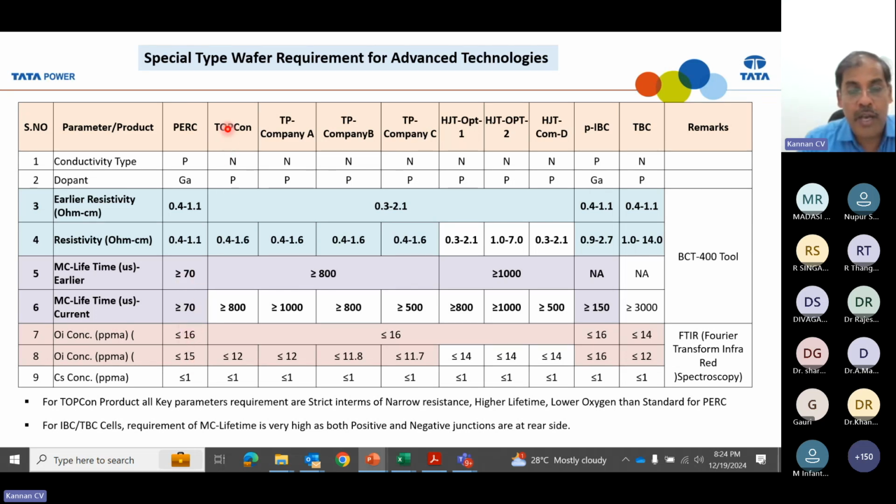But when you go for high efficiency technology, TOPCon, which is currently the mainstream high efficiency technology, and HJT, all these new technologies are based on N-type product. They are not using p-type based substrate. A few years before, all the grown ingots were p-type. Now the entire industry is moving from p-type ingot growth to n-type ingot growth, because n-type based wafer technology is offering higher efficiency.